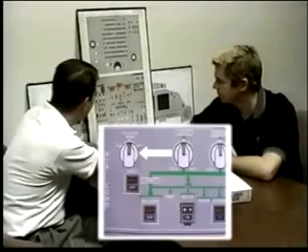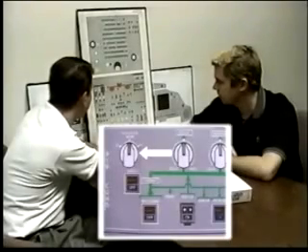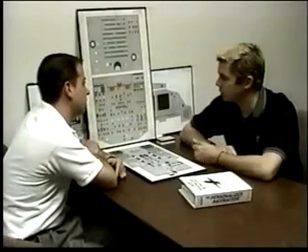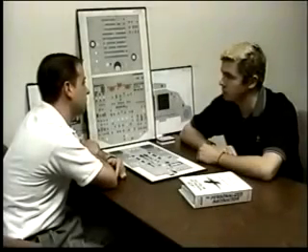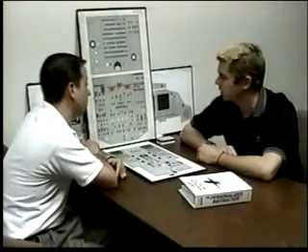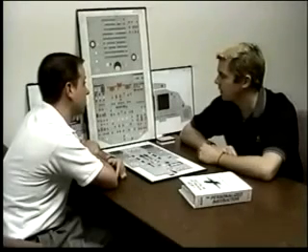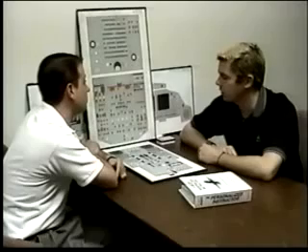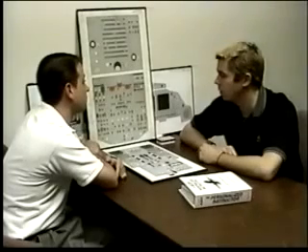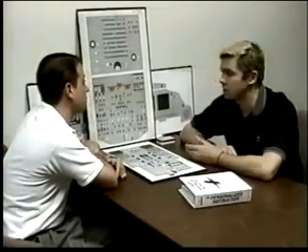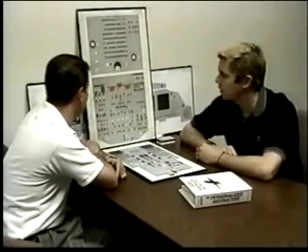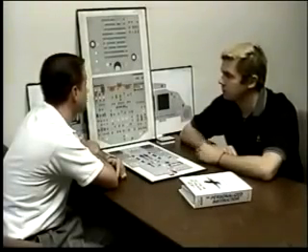Pack flow selector valve. You have 3 positions: low, normal, high. Describe to me the pack flow selector valve. In low, I would select the low whenever I had a passenger load less than 115 passengers. I'd select the high anytime I had a situation where the packs weren't supplying enough cooling to the back. Anytime I shifted to low and the system thought it needed more, it would shift higher. In other words, if I'm on single pack operation or if I'm using APU bleed, it would shift higher. If I were in high though, it'll never shift lower.